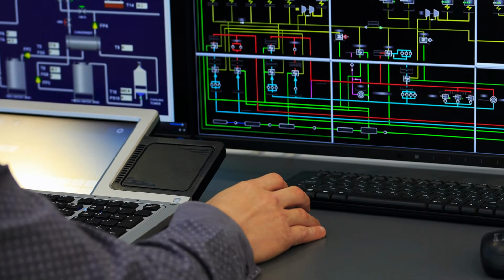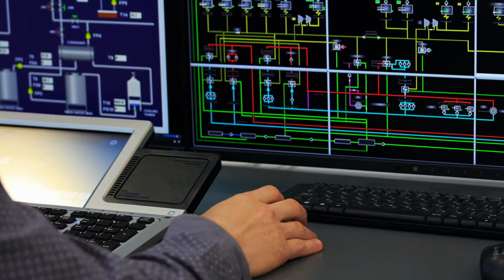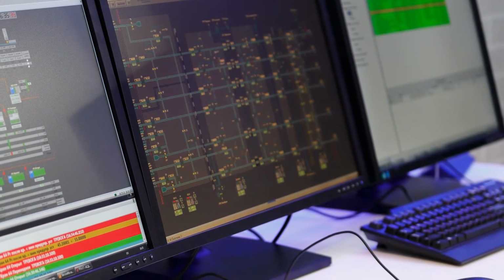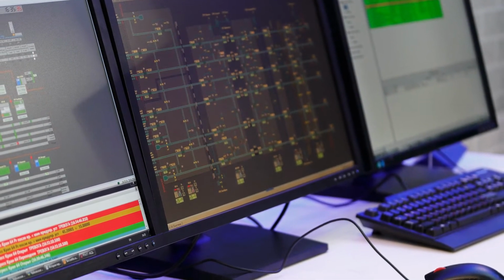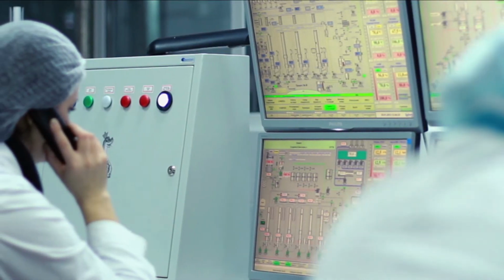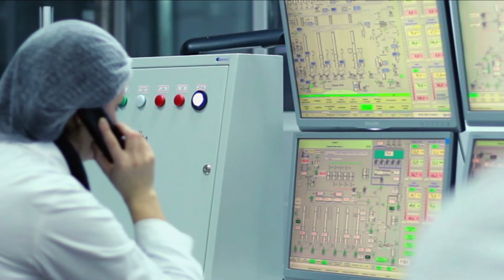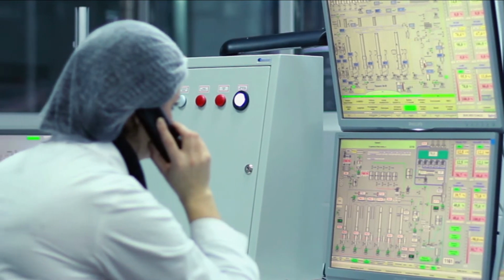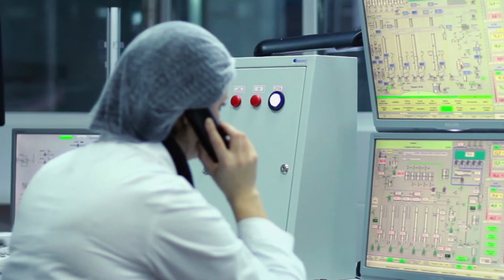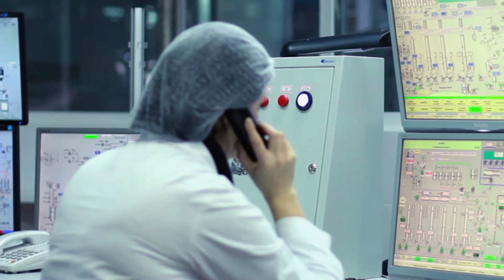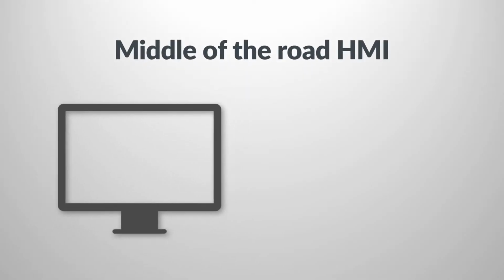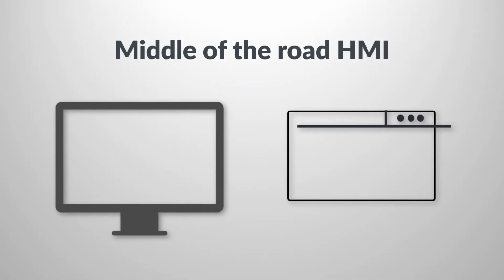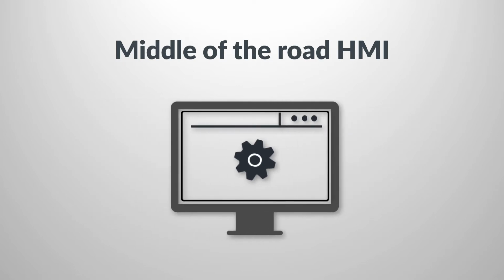As the machine application requirements move to more graphical screens, buttons, alarm history, recipe functions, trends, and historian functionality, such as those commonly offered by the PLC vendors, HMI software functionality increases. These middle-of-the-road HMIs, usually embedded PCs, still closely tie the HMI hardware and software together.